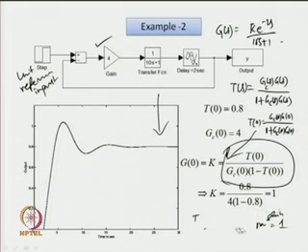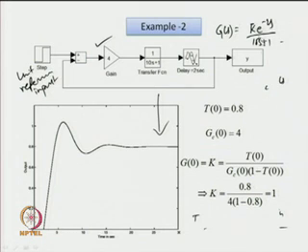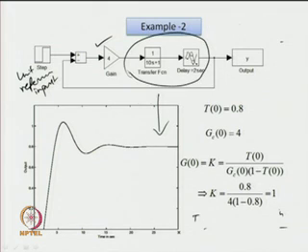Once the steady state gain has been found, again we will try to find the remaining parameters of the transfer function model. How are we going to model the dynamics of this process? Let us assume some specified transfer function form. Let the model of this process dynamics be represented by k e to the power minus θs upon T1 s plus 1.